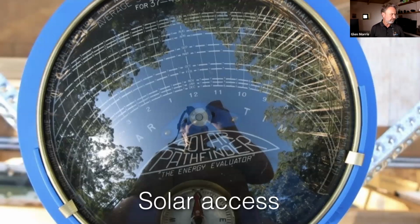and safety. So finishing off on this, shade analysis is a very useful tool to have when designing a system where it's less than ideal. There are many tools available for this. Some of them as simple as an app. Personally, I use an app called Sunseeker on my phone. Really, it just tells you where the sun will be at different times of the day throughout the year, and you can use the camera and the compass in your phone. It doesn't give you an energy calculation, but it just tells you position. So those are useful tools.